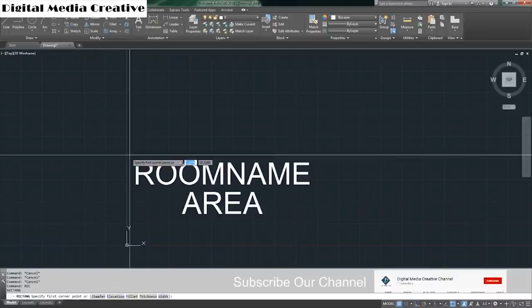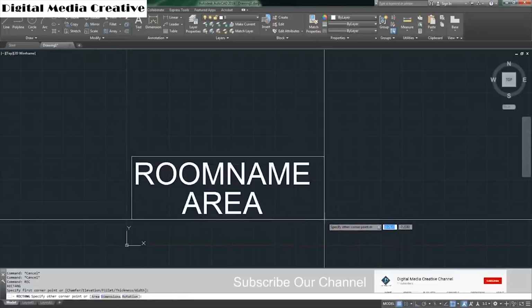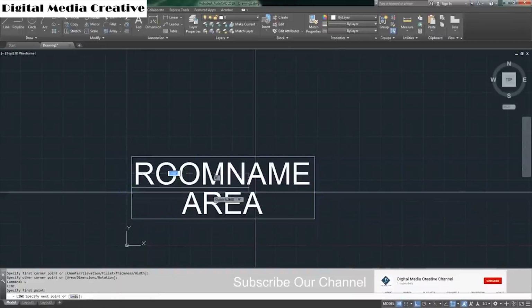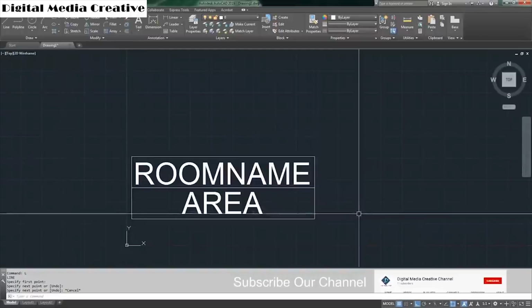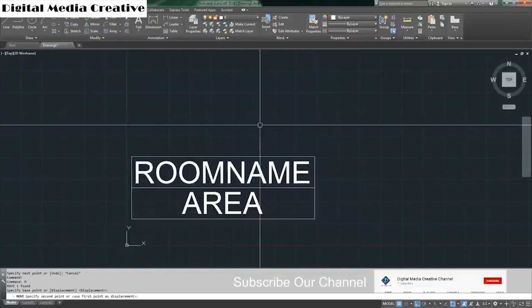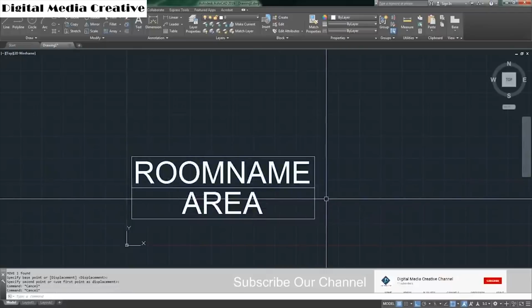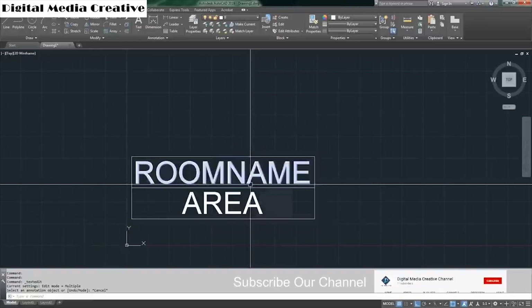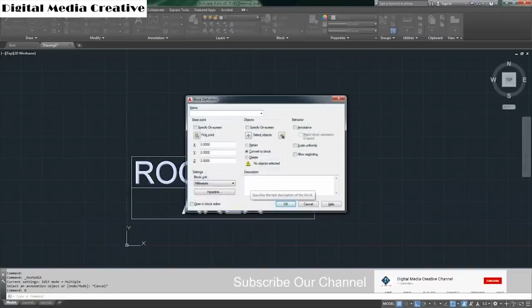And then we make a rectangle, some line work to make the tag look good. Now the next step, we need to make a block for this. You can make a block, type B, then name it room tag, pick the insertion point, make it center, and select objects.